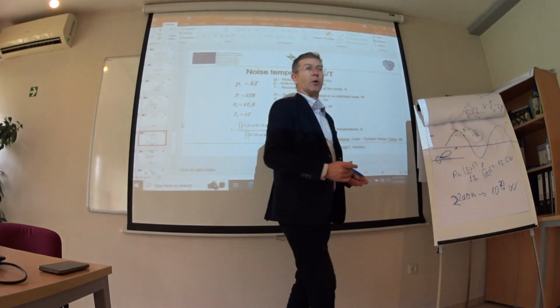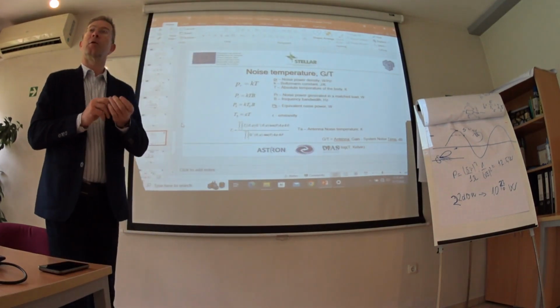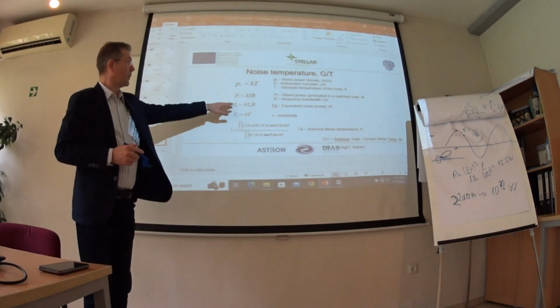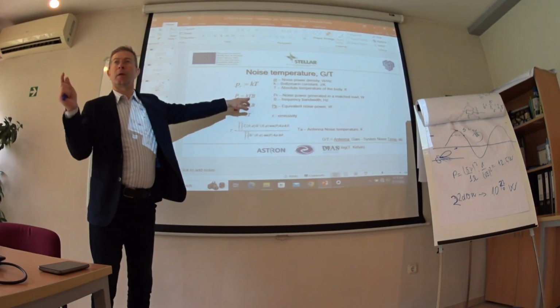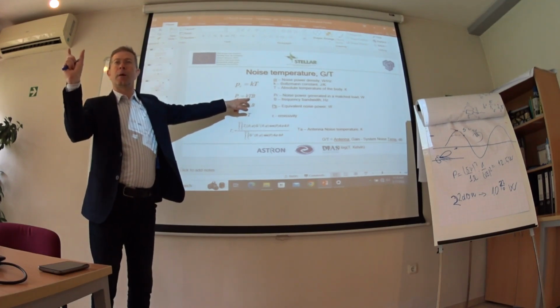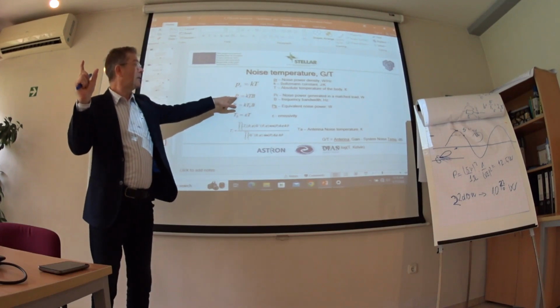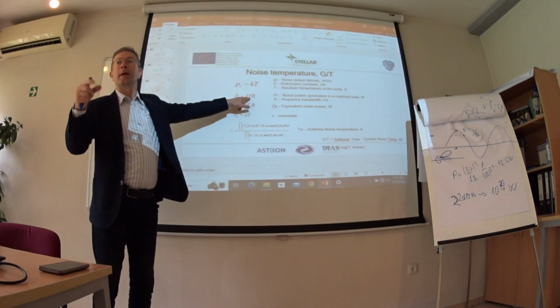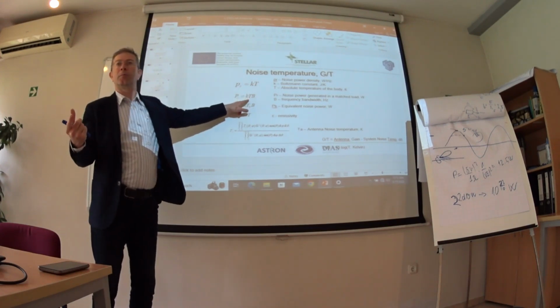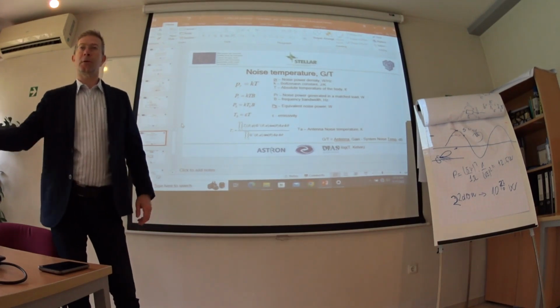So all these three things sum up as a noise power, which can be expressed with that noise temperature. And we say we are monitoring a bandwidth of 1 megahertz, and our antenna sees that power, and that power will be expressed as a noise temperature. We say antenna is hot 20 kelvins, or antenna is hot 30 kelvins.